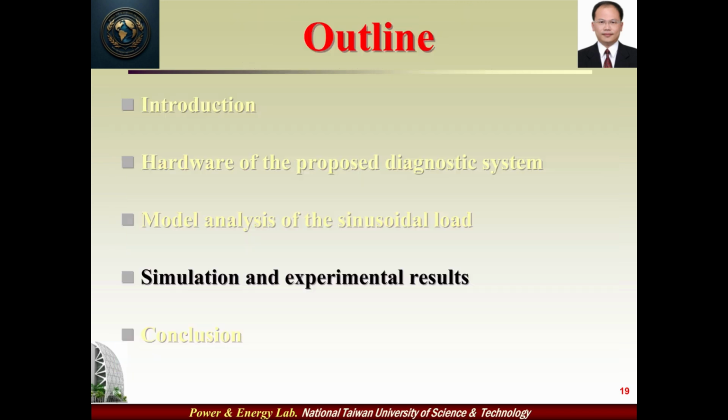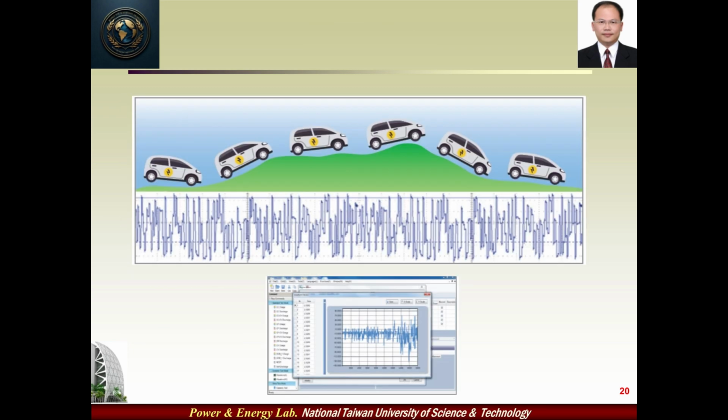In this section, we will show some experiments. When a battery-powered device or electric vehicle is powered by a battery module, the actual load current is irregular or non-periodic. Therefore, it is not easy to simulate the practical working current of the power battery for online tests. The sinusoidal current waveform has inherent wide-range slew rate characteristics, which is suitable for simulating the work conditions. Next, we will demonstrate some experiments using the proposed sinusoidal load.